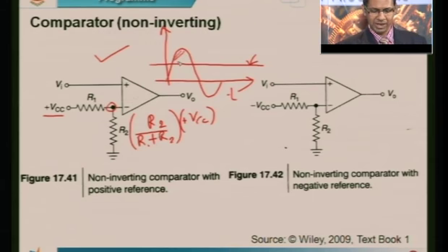So in this shaded region that I am trying to show, what exactly is happening? In this entire region, your input voltage is above the reference voltage. So whenever this happens, the output saturates to plus Vsat. And whenever it does not happen, that is whenever your input is below this line called Vref, then your output becomes minus Vsat.